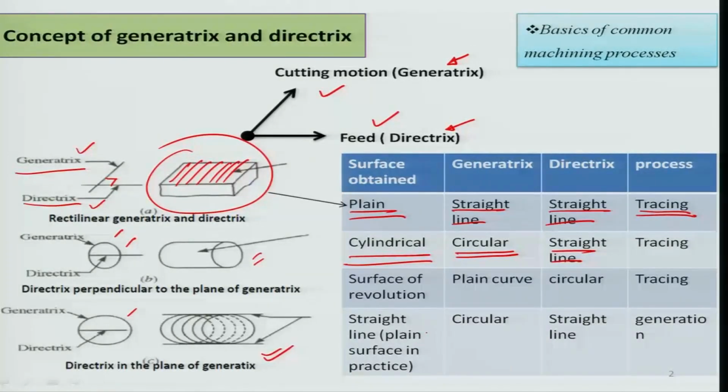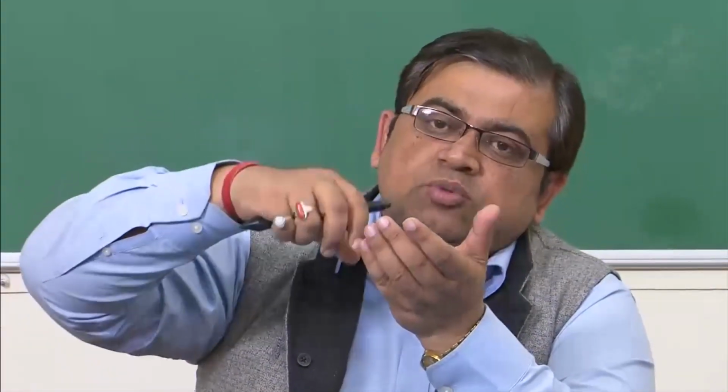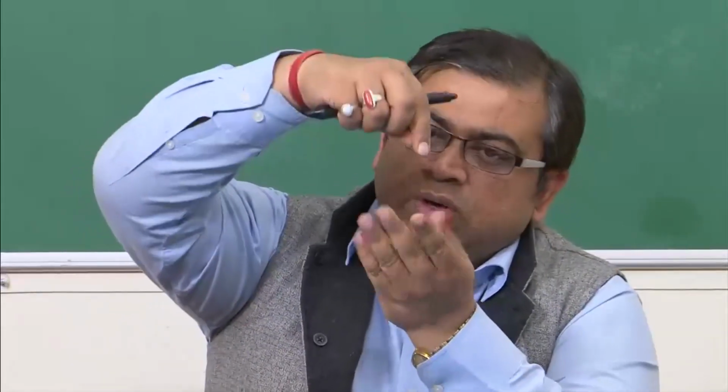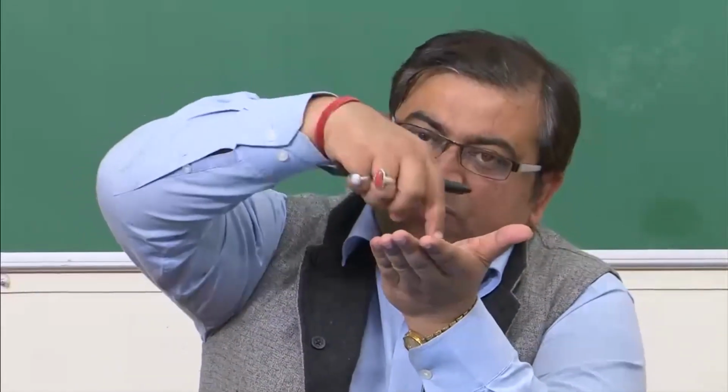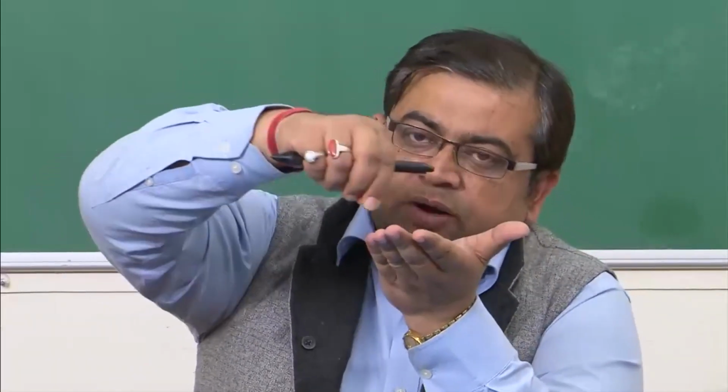So, in a milling system you have, let us say, a circular motion, and the cutting motion is really along a circle, and the cutting velocity and the way that the chips get formulated is, particularly in a face milling operation, how the tool engages in a circular manner at different points. It is a multiple point cutting tool, so that you can have chip formations along that circle, and then you are basically moving it in a direction perpendicular to the direction of the cutting velocity, and so you get a plane surface based on these two motions.